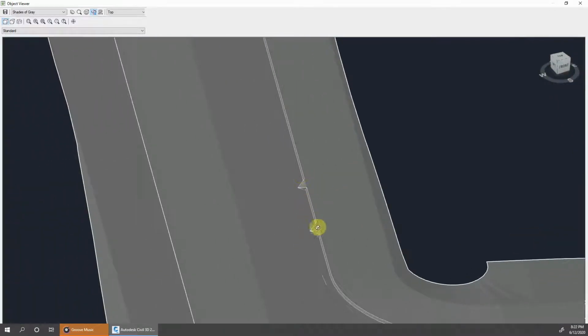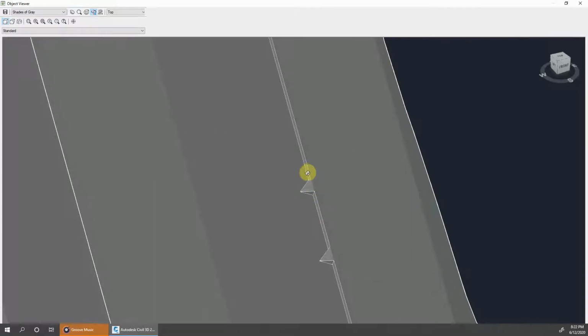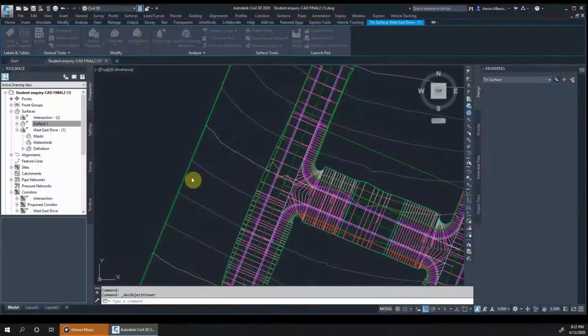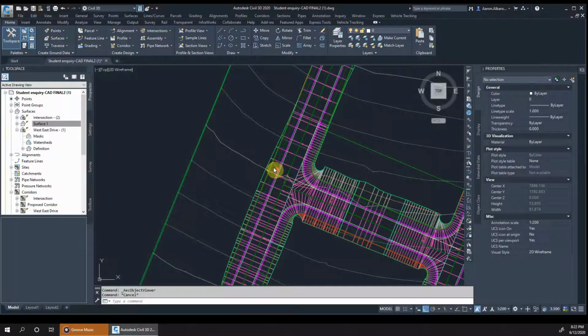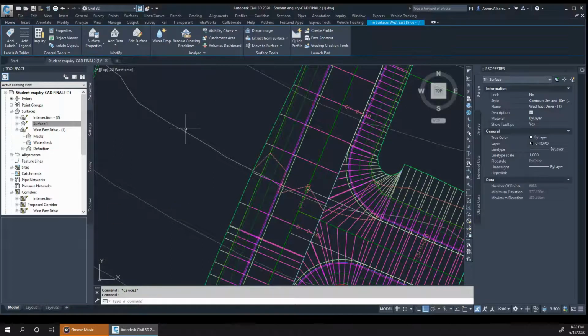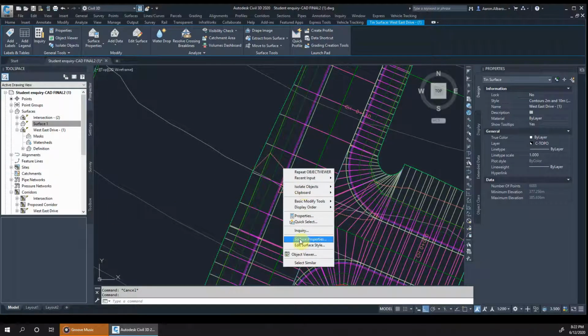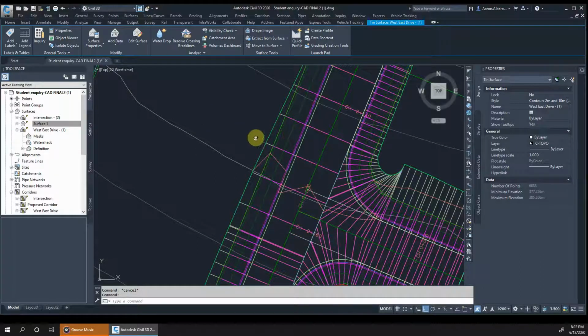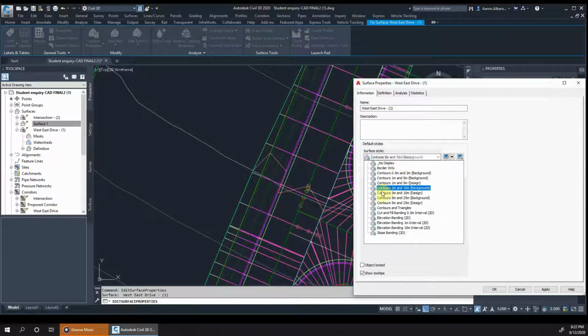If you have these issues here, it's simply that the line should continue without drawing triangulation to this point there. To fix that quickly, I have to put this actual surface in triangulation, rather than being in a contour format currently. So in the surface properties, I've got to choose the arrangement, which is in contours now.